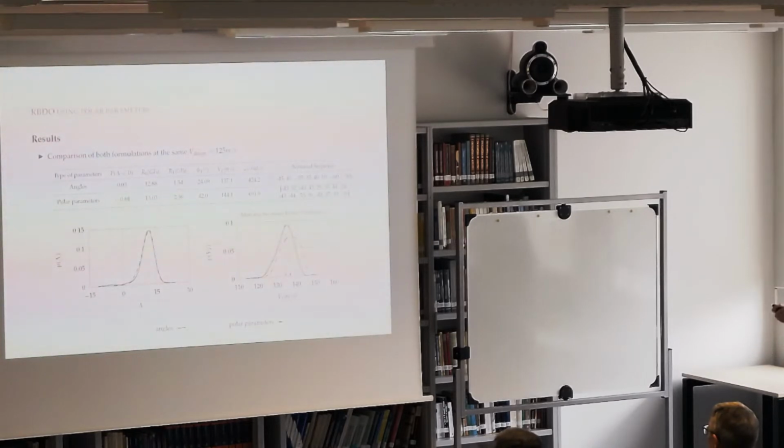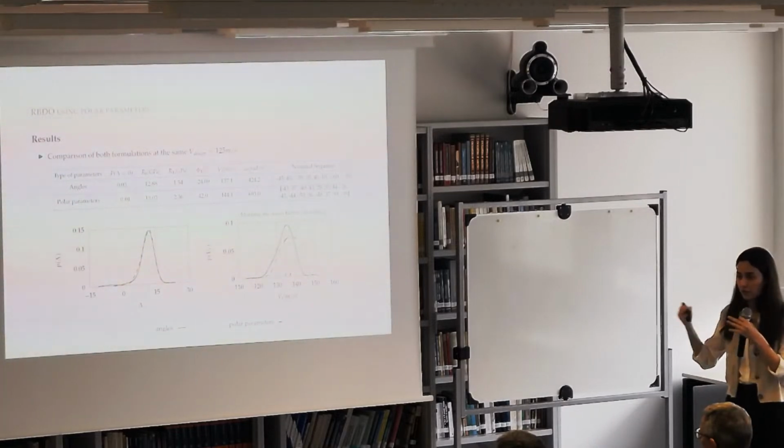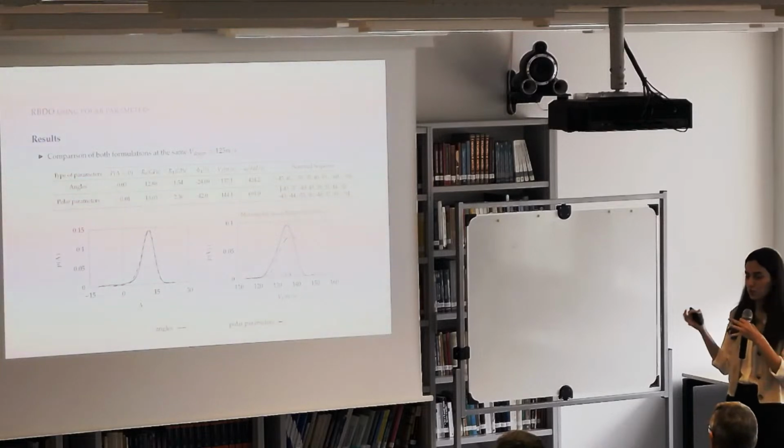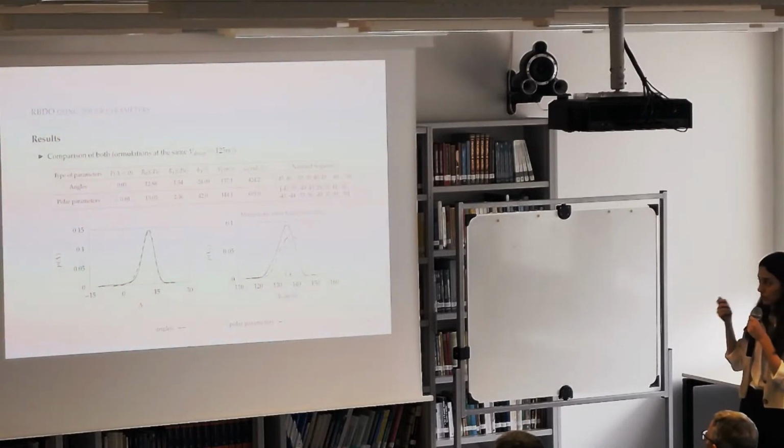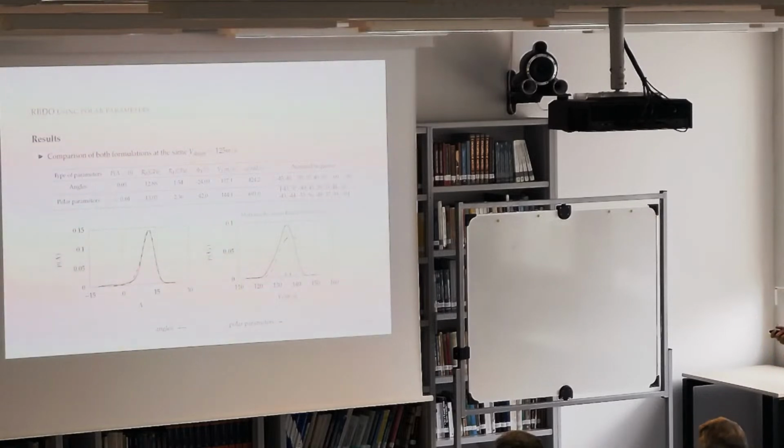Here I have compared the results I obtained with the ply angles and the polar parameters. I can see that using the polar parameters, I have further reduced the probability of failure. Using the polar parameters, I have limited my optimization domain to only orthotropy. So now I have more control over my elastic properties. And I can see that I have even increased the value of my flutter velocity from 137 to 144.